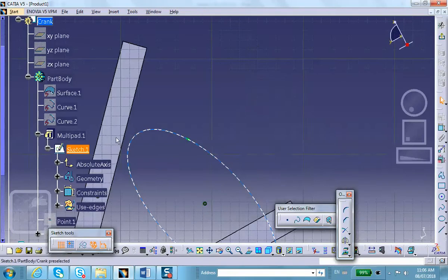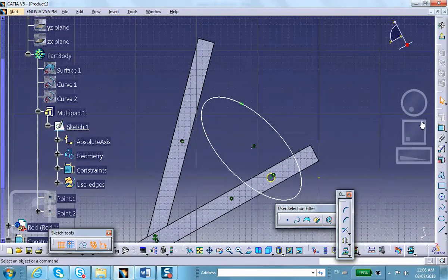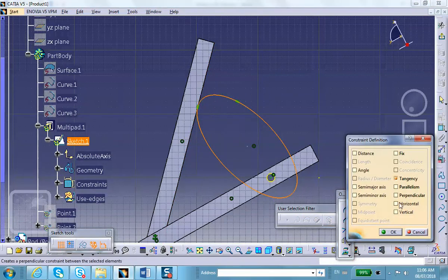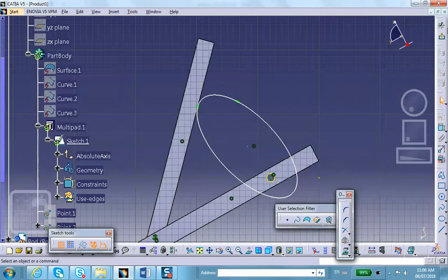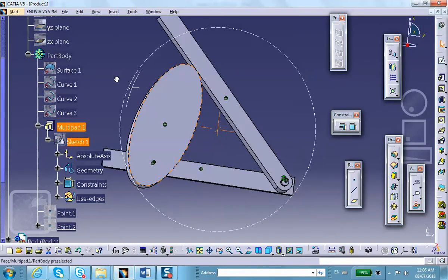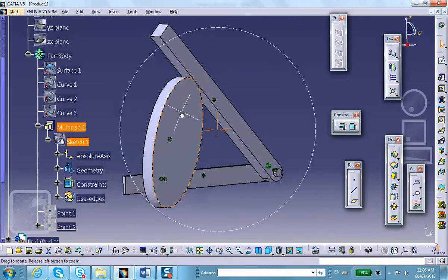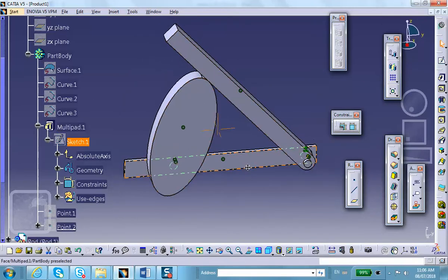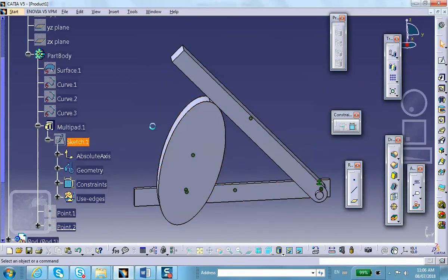So we go to that sketch. Let's select this ellipse, control that edge. Let's see if we can make it tangent. Okay, if it doesn't work, try to change them in the reverse order. Okay, there we are, you see? Everything is alright. Unfortunately, if you cannot put these two together, there's no way you can do the rest of the problem. But this was nothing new, we had done it in class.